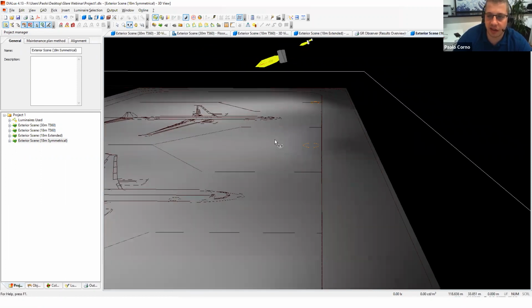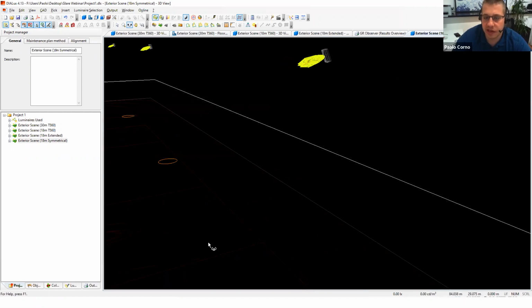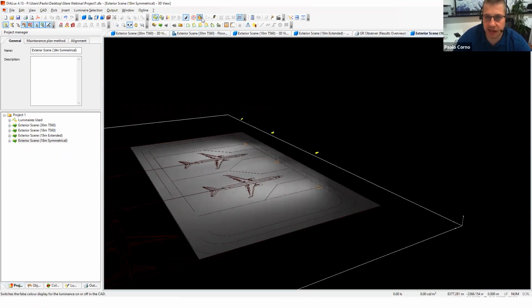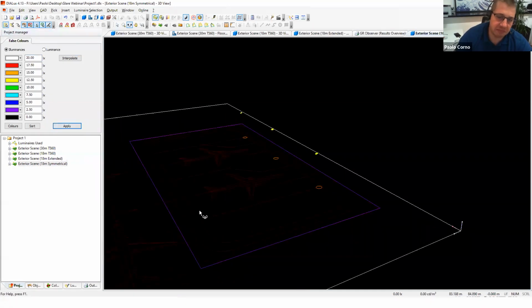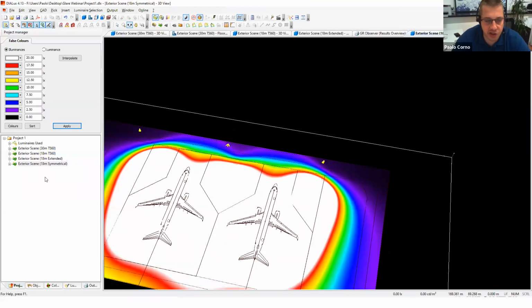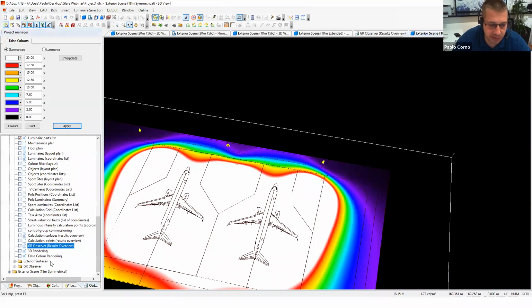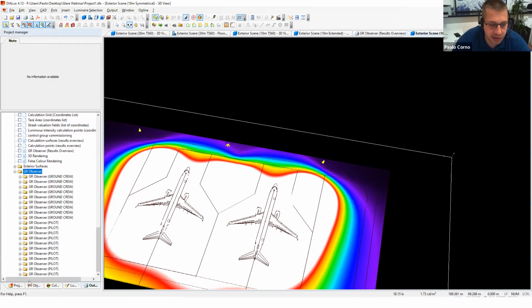We don't have a lamp sitting flat. We have a directional lens, which is pointed directly at areas on our apron. You can see that the light distribution is quite good, so it's something you could see in an installation at the airport. But let's see what happens to our glare rating when we switch from an asymmetrical to a symmetrical light source.